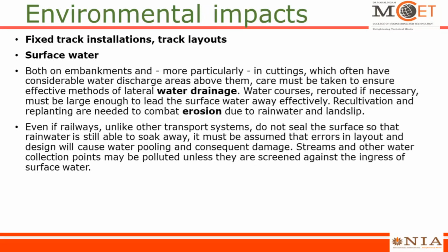Second is the surface water problem, both on embankments and more particularly in cuttings. Actually, the embankment is filling up. You have cutting and you have filling up. So when you excavate some of the soil you are cutting, that soil can be used for filling up somewhere else, right? The filling up can be above the surface of the land also, right? So that is the embankment.